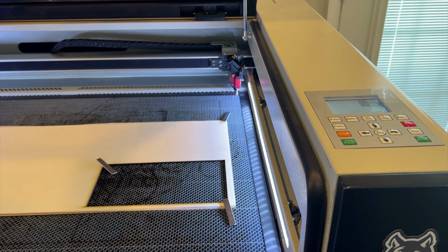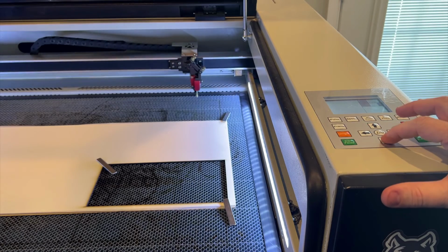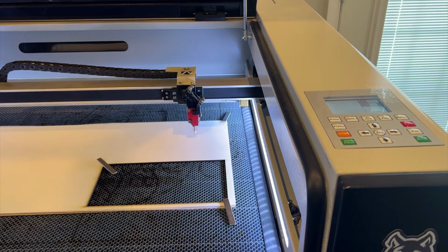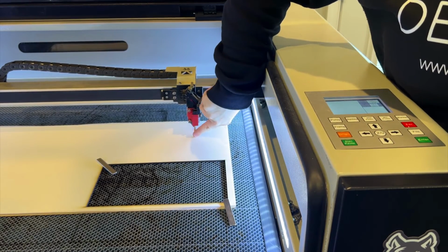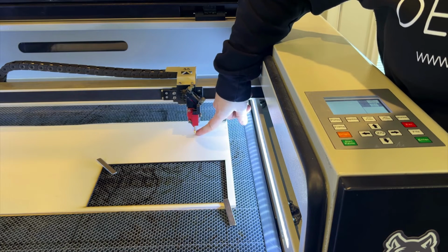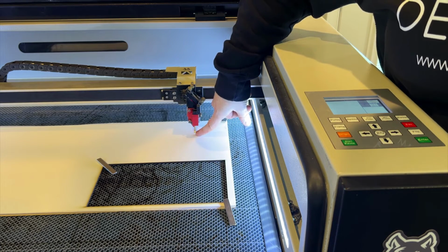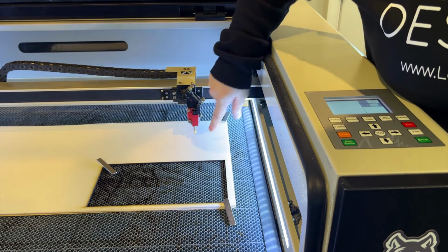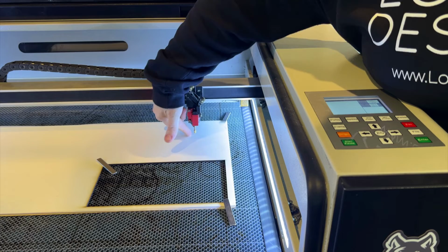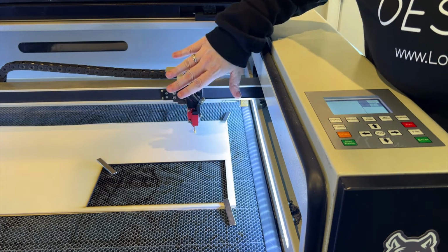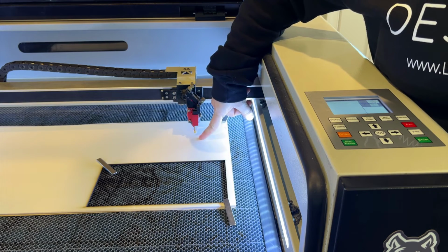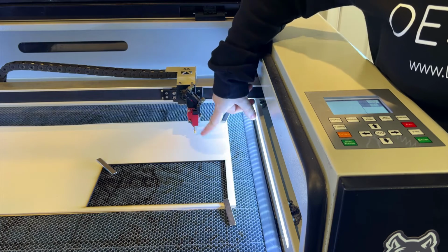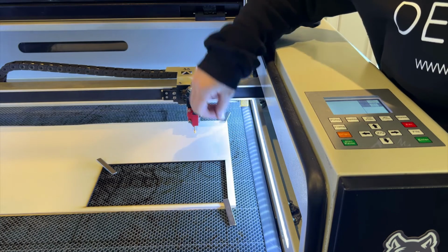So the very first thing that I want to show you is how to use the autofocus. And what you do for that is you just move the red dot over the material. You make sure that not only just the red dot is over the material, but you want your focus pin right here to be over the material as well. What will happen here is when this judges the height of the material, it's going to lower the gantry. This little pin is going to get pressed up against the material like this, and it's going to tell the machine that this is where the material is. You want to make sure that this is always over the material and not over your crumb tray, because if this goes into the crumb tray, you will have a collision and then you will panic.